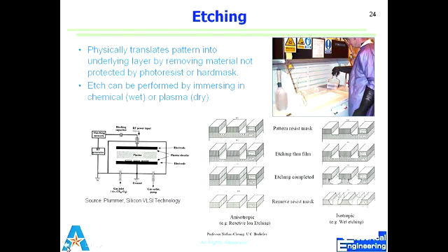So, a couple of examples of etch. Probably we'll stop on this one. This shows us anisotropic etch versus isotropic etch. We start with the same etch window, but the recipe in this case is going in all directions. What we end up with doesn't have high aspect ratio. But if we have a recipe which is anisotropic, we end up with features with very straight walls.